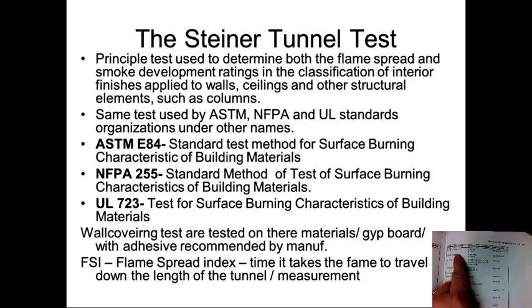So when we said the Steiner tunnel test, remember it says the ASTM E84, which is the standard test method for surface burning characteristics of building materials. And it gives us here UL 723, which is the test for surface burning characteristics of building materials. And they utilize the NFPA 255, which is the standard method of test of surface burning characteristics of building materials. Wall covering tests are tested on their materials, chipboard with adhesive recommended by manufacturers.